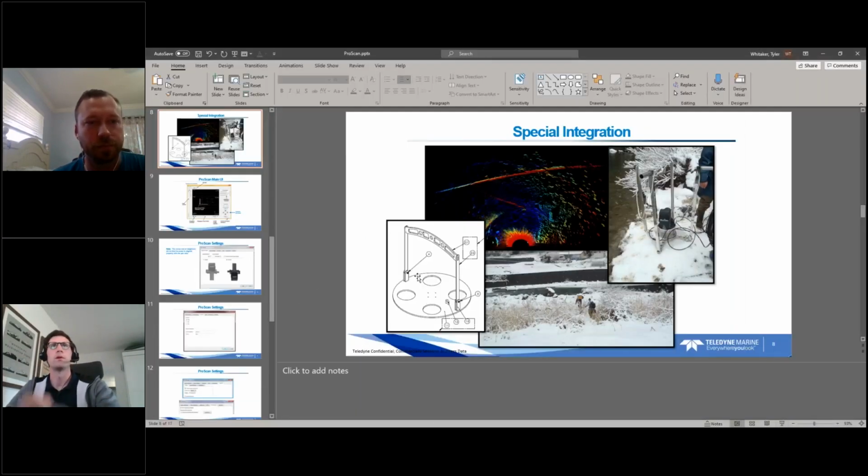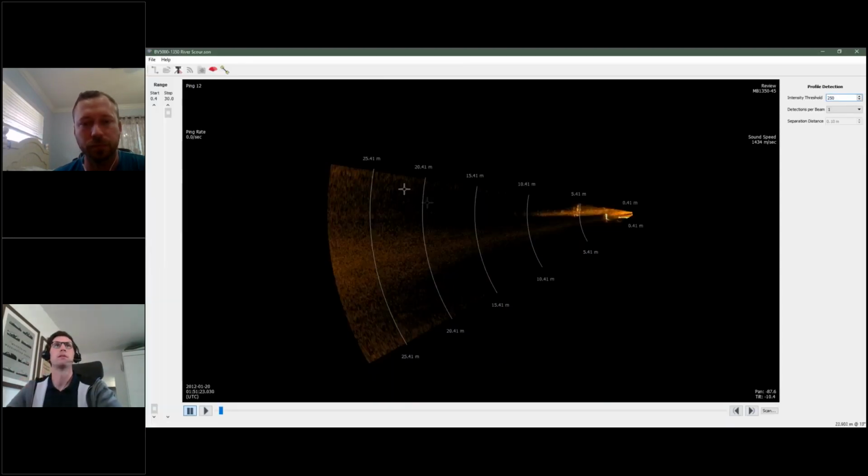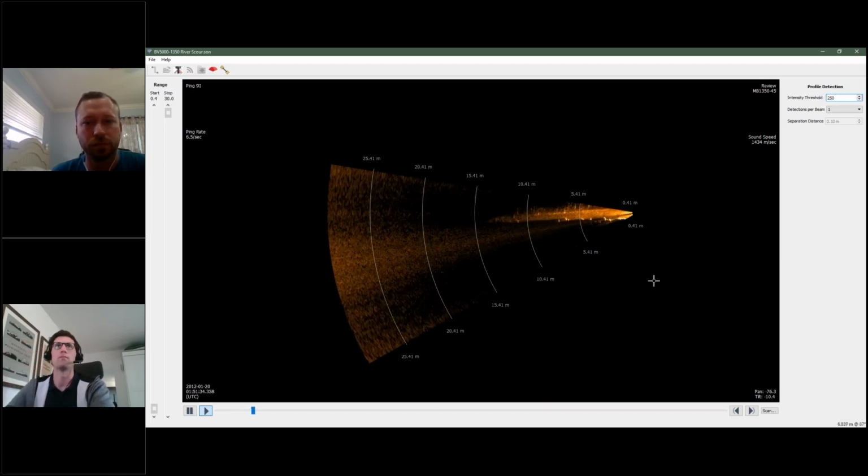So very shallow river. We're going to look at this actual raw data that was collected during this little survey. This would have been exactly what John or whoever else was there would have seen during acquisition, basically this Proscan view. So I am playing now. We don't see much. We do see the image updating, but we can immediately see this is very shallow. This is very noisy. It's a river. Rivers typically have a lot of sediment, particulate floating around, high turbidity. So very noisy environment, and we can tell that just from the raw 2D imagery here.